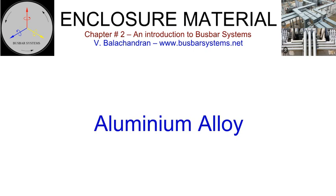Busbar systems manufactured with aluminium enclosures are lighter. Aluminium enclosures provide excellent earth continuity. Special aluminium alloys are used when enclosures are exposed to saline atmospheres, as in installations in coastal areas, ships, and offshore platforms, or when the gas-insulated bus are buried underground.